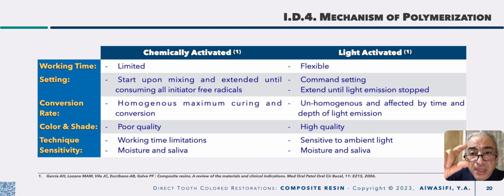If the material is thicker than 2 millimeters, then the part beyond this 2 millimeters will not have enough light activation to break down its camphorquinone initiator to get the reaction and get the maximum properties.